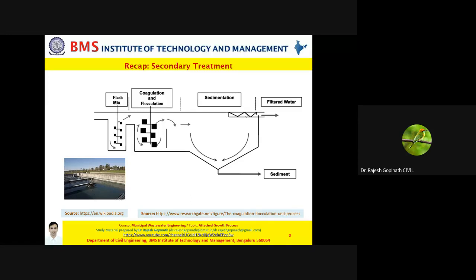When I say chemical treatment, I mean clariflocculation. That is, you add coagulants, you have a rapid mix, a gentle mix, and then quiescent settling. However, you shall go for this only if the circumstances demand it. Please note, if you go for chemical treatment as a part of your secondary treatment, then you cannot continue with biological treatment, because the chemicals you have used would have destroyed all the microorganisms. With this basic fundamental concept, let us start today's session.